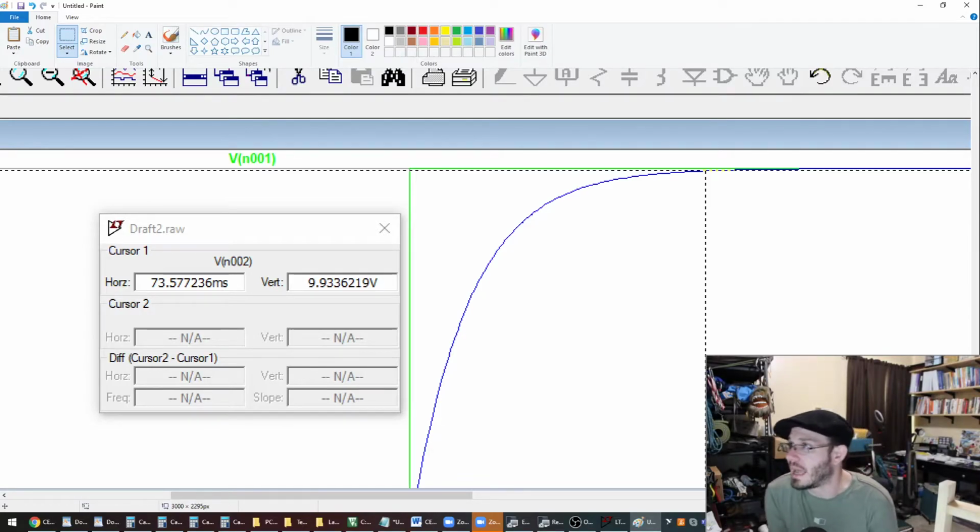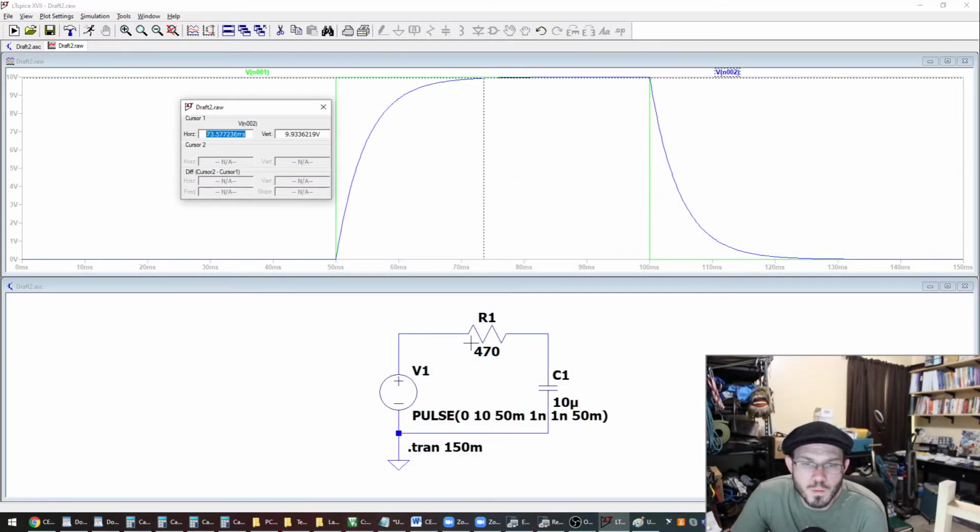if I'm below 10. Okay, so then the voltage across the resistor would be 0? Yeah. And the capacitor is fully charged? Yeah. Want to see that? Okay. So let's go ahead. Let's look at the current going through this. Yeah, tau is 4.7 milliseconds. That's our time constant.